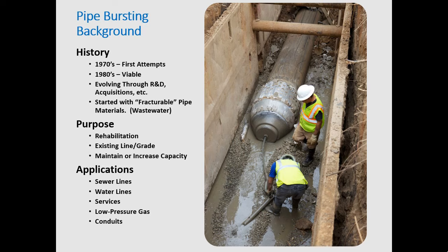It started with the wastewater side. This is the only trenchless technology where you actually, like I said, increase the capacity. So in an existing developed area, this is real popular. This is, again, why it kind of started in Europe. In a densely populated area, all of a sudden they put in a high rise, and your old 8-inch wastewater collection system cannot convey the flows that you're seeing with this new 10-story high rise. So downtown urban areas are where this really came into effect.